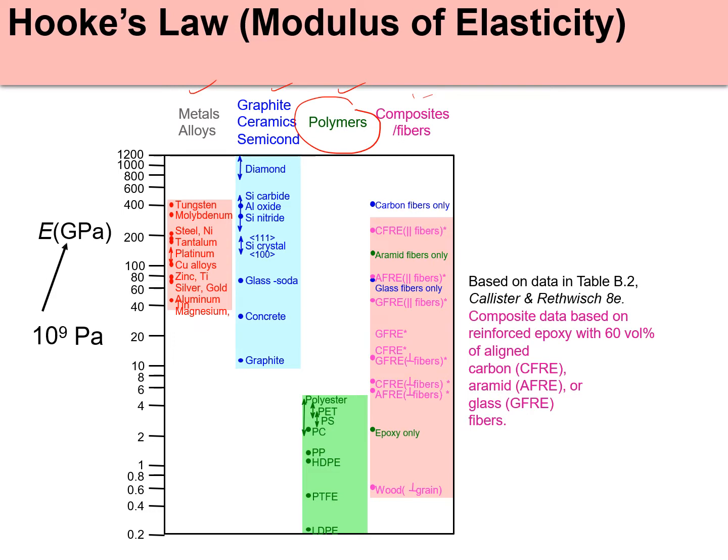However, we can see the Young modulus for the composite, especially for GFRC or maybe carbon, lies between the values for the polymer matrix and the fiber phases. It depends on how much fiber or reinforcement content there is. The more the fiber or reinforcement content, the better the Young modulus, because it gives you high stiffness.